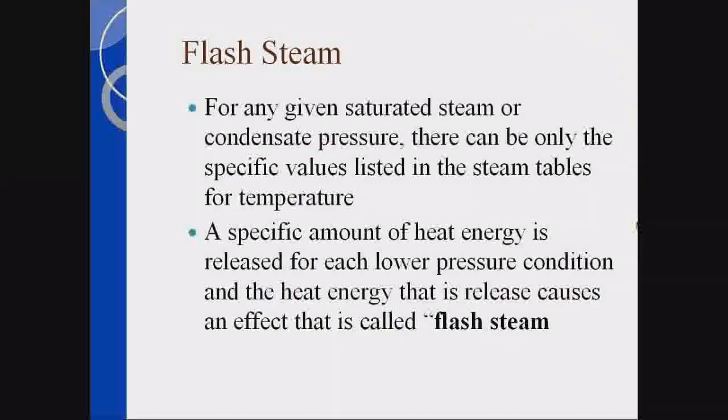For any given saturated steam or condensate pressure, there can only be specific values, listed in the steam table. We call it the saturated steam tables. On release to each lower pressure condition, the heat energy that is released is what we call flash steam.